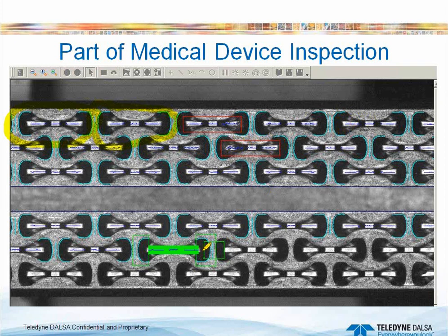So if you see the region of interest, there's a contour on the end, and then there's the inspection to find those nice clear areas. If there's any dark, like in this case, there are some contaminants on the object. So again, when you're trying to inspect 100, 60, 80, whatever, same objects, it makes it easy because now the image is always consistent. All you have to do is develop one tool and put it in a loop, which you increment the address to go to the next location.